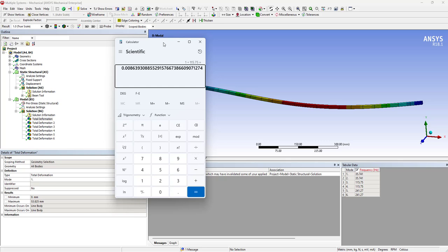this into further, at least 20 steps so that we can capture the details of the fluctuation with time. So the time step should be less than this value. Let's divide this by 20, and there we have 0.0004 seconds, and we can use 5 seconds as well.